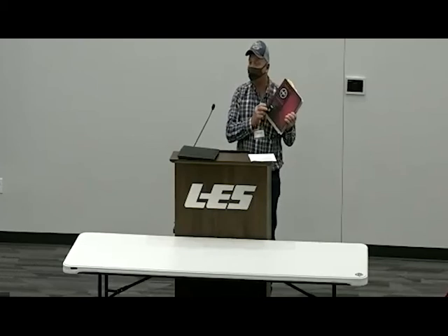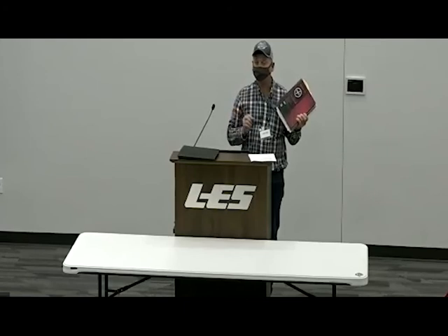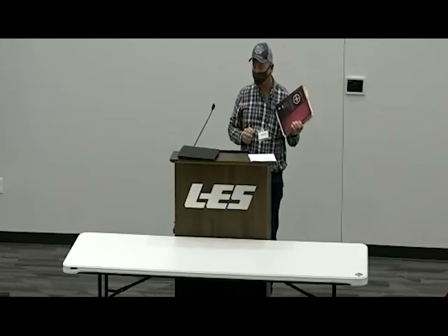First thing I want to talk about is normally the PV salesman, whoever's selling the system, they are not usually wiring it. And I hope they're not, because usually they're not licensed. But if they are, I really suggest you get the handbook. We're on the 2017. Article 690 has 8 parts to it. It's very short, very easy to read, and it really saves you from having callbacks. Garrett was talking about a one-line diagram, very important. And they're required on every system.